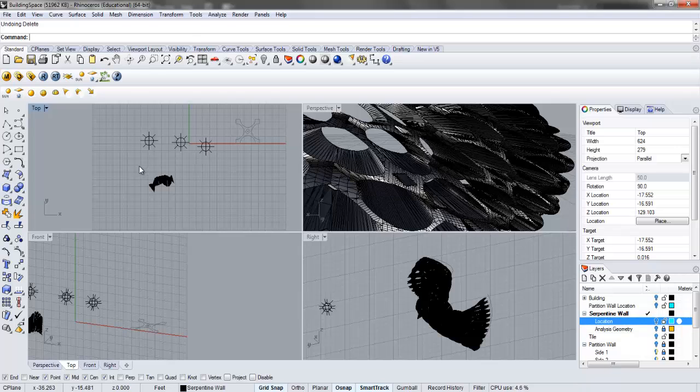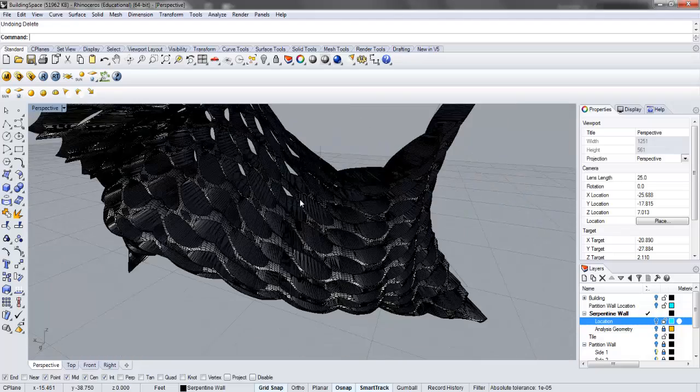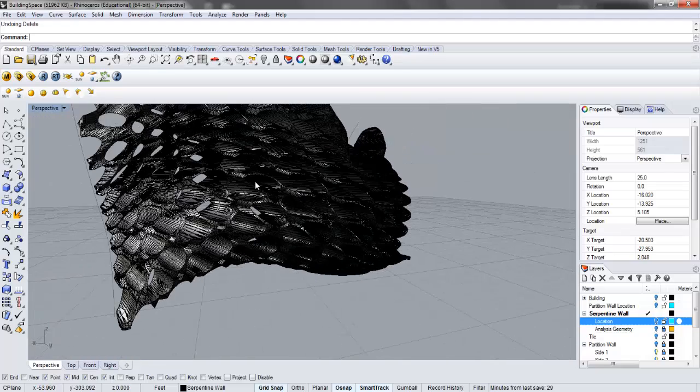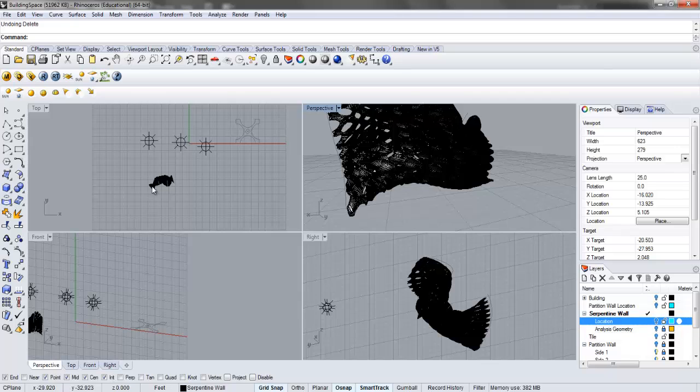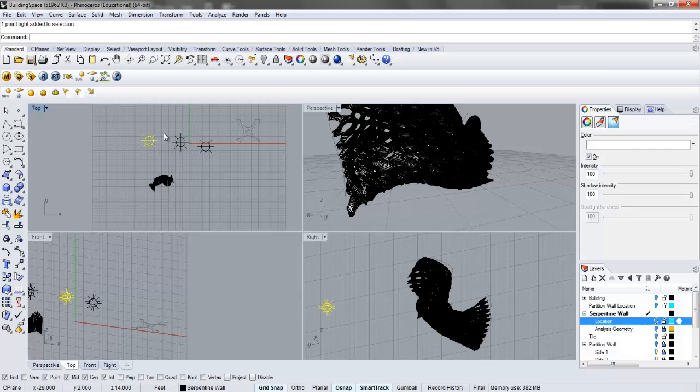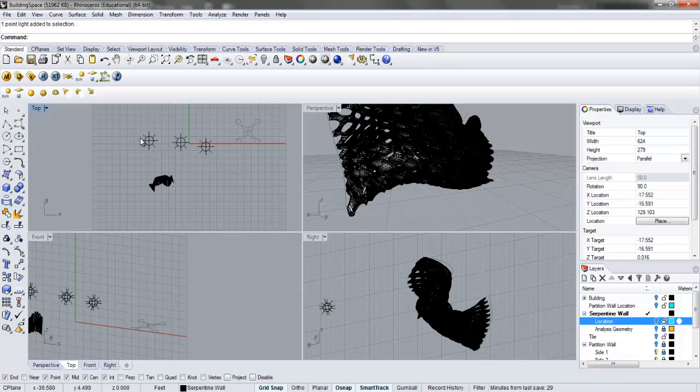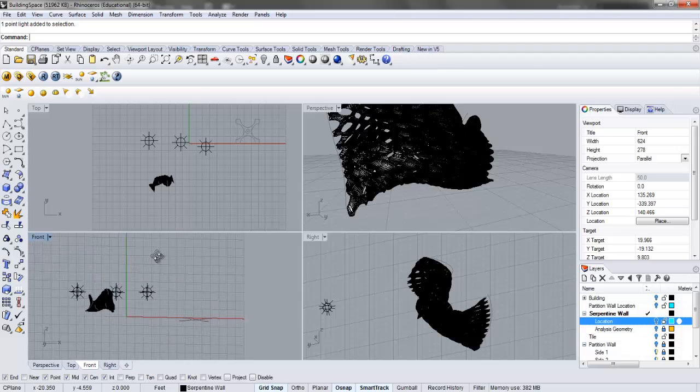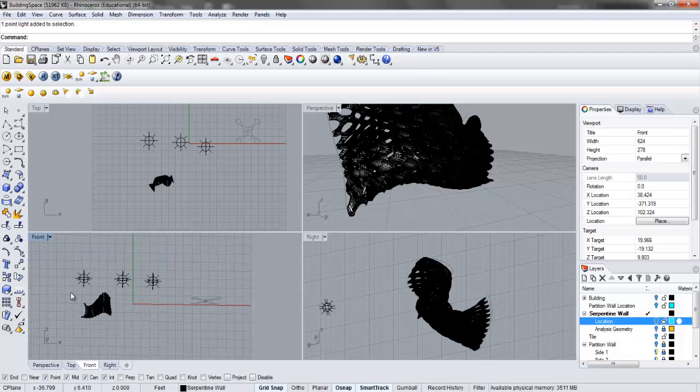Okay, so what I've done here is set up a perspective, and I've just rendered it out, zooming in somewhere on my wall. I then went ahead and placed a couple of lights. These are Omni lights, or point lights; you get them from clicking and holding right here. These will project light in all directions. I placed three of them in plan, and then I pulled those up. If we rotate around here, you can see that I pulled this up off the ground, so we're getting some light at around eye level for the wall, about 6 feet up in the air.